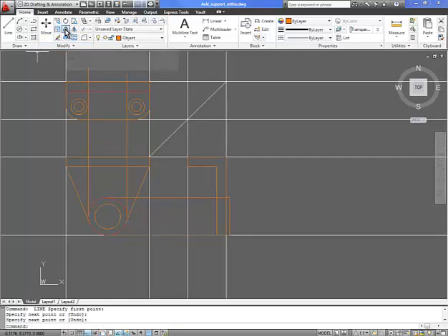Also, we're going to go to the offset tool, which is 0.125. We accept it. We go that way. Now we can trim these lines also. This line is trim, this line, and this line. So now we have the boss. This takes out for the bushing to sit against. And the same on this one.